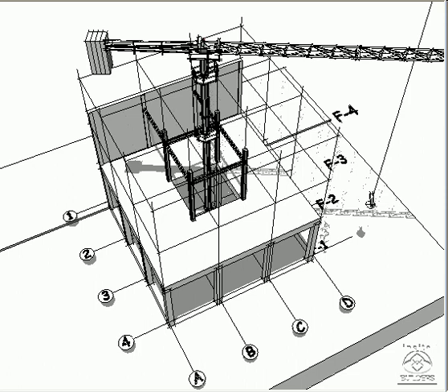Most ironworkers would freak out at the idea of going up and down the steel to set first columns and then beams. They would want to set all of the columns at one time. The idea here is to establish a supporting core first. This stabilizes the wall and the center of the steel.